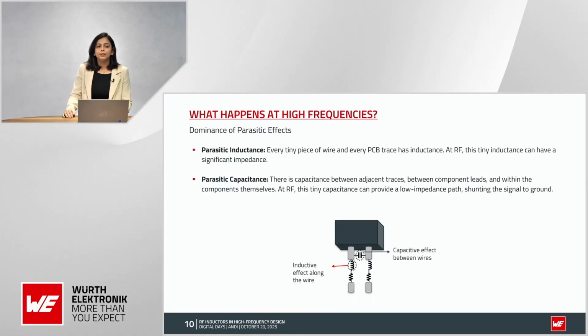Second thing, the parasitic effects start dominating the circuit. Now, these parasitic effects are the unwanted stray properties of a real-world component like an inductor or capacitor that are not part of its intended function, but they're always present. At low frequencies, their effects are negligible, but as we move towards high frequencies, they start dominating the circuit. So while designing a high frequency circuit, one of the main requirements is to minimize these parasitic effects.